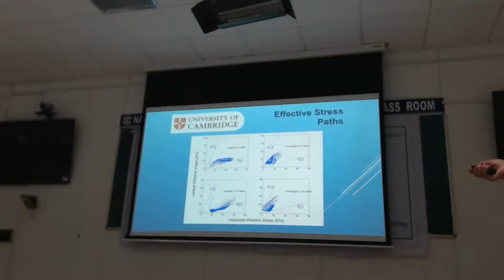On the downslope side, I would expect most of the time it to be at Ka, but it is not. It starts nicely there, but as the cycles progress, it's trying to get more towards Kp. That's because of those big suctions we are seeing. The big suction that is developing on the downslope side is pulling on the pile. And that's why it's trying to take it towards Kp, and that's why we got all this extra behavior.